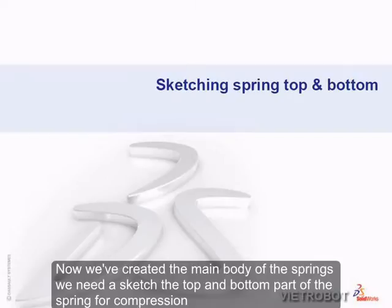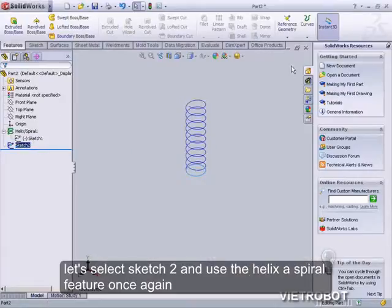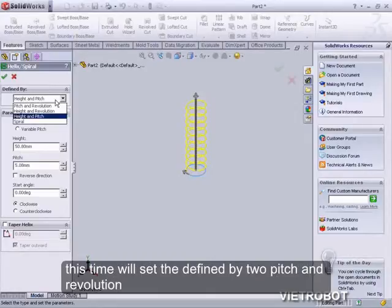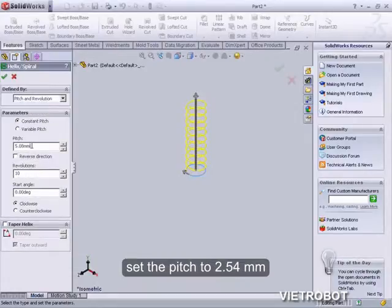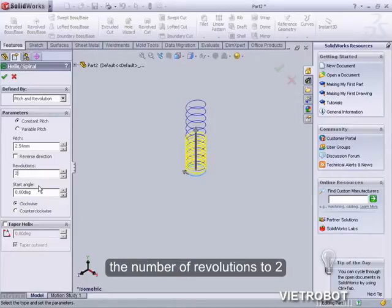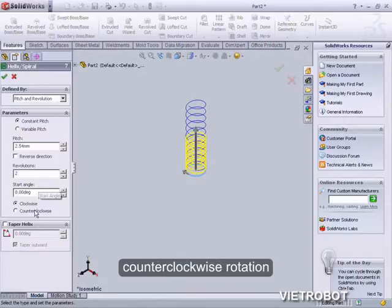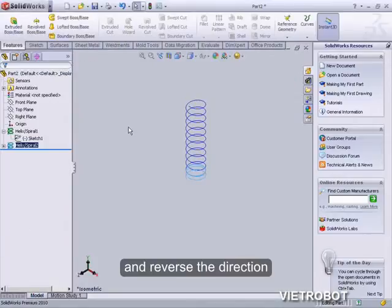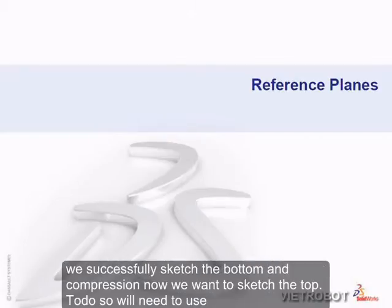Now that we have created the main body of the spring, we need to sketch the top and bottom part of the spring for compression. Let's select Sketch 2 and use the Helix and Spiral feature once again. This time we'll set the Define By to Pitch and Revolution. Set the pitch to 2.54 millimeters. The number of revolutions to 2. Counterclockwise rotation. Start angle at 0 degrees. And reverse the direction. We've successfully sketched the bottom compression.